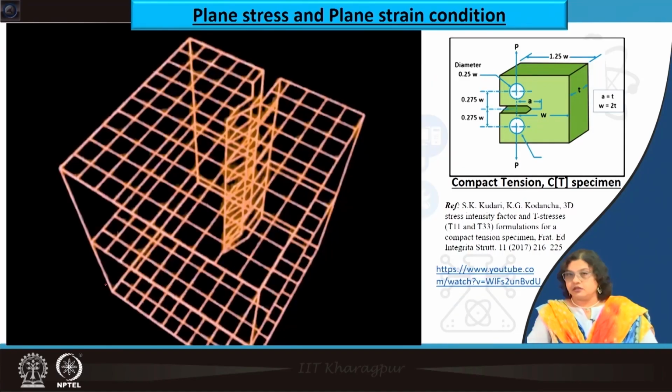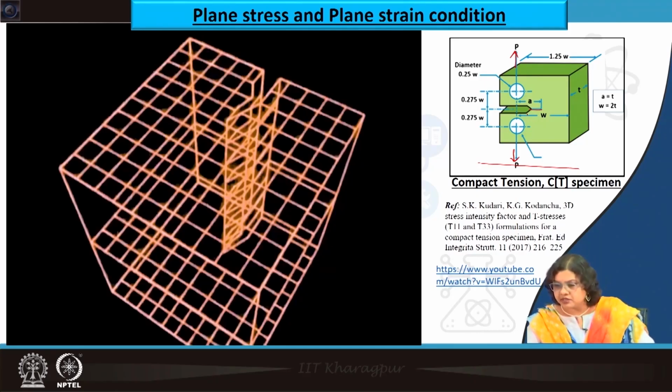Okay. So, here is a video which explains how the plane strain and the plane stress mechanisms are active. This is particularly done on a compact tension specimen, which is typically used for fracture toughness testing. So, this is a 3-dimensional specimen that you can look for. This one is quite thick here, and when we are loading it along this direction, the crack, which is perpendicular to this loading direction, expands along this direction, and all the activities are happening in this zone ahead of the crack tip. So, let us see how this works in this video.